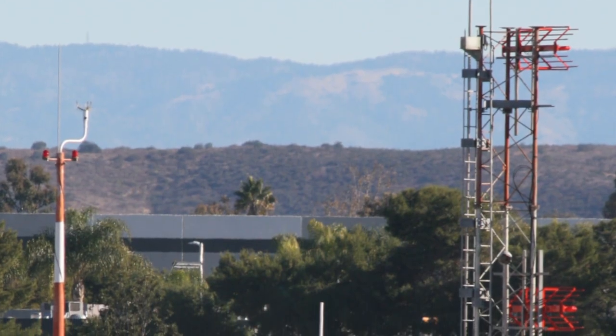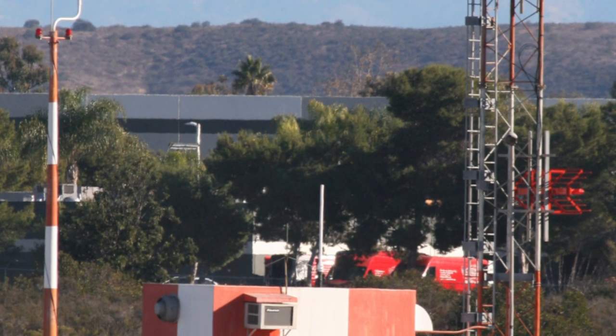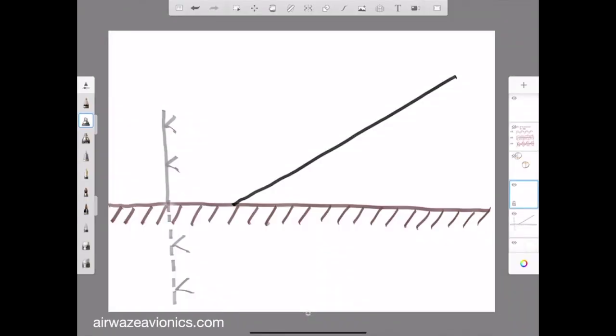Depending on the heights of the antennas above the ground and each other, the angle of the resulting glideslope beam can be adjusted during installation to suit the particular runway location. Typically, the glideslope will point up from the touchdown point at approximately 3 degrees. The transmitted signal is a vertically polarized continuous wave AM modulated UHF signal.